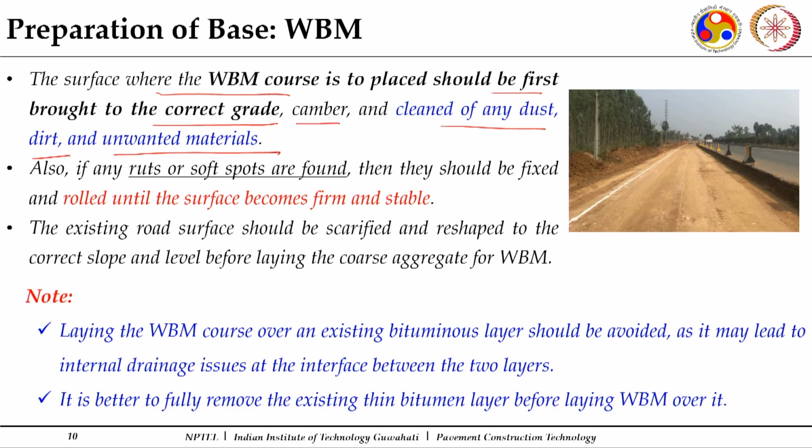So, before you go for the construction of the waterborne macadam, it is important that you aerate that particular layer again. If material is required, you need to mix it in, and then you compact it to bring it to the required density and grade before you put up your next waterborne macadam course. Also, if any ruts or soft spots are formed, they should be fixed and rolled until the surface becomes firm and stable to receive the waterborne macadam course.